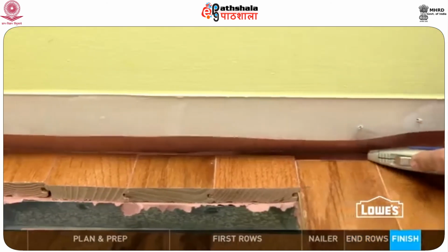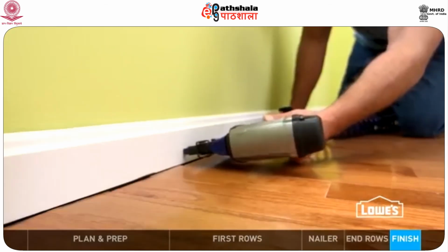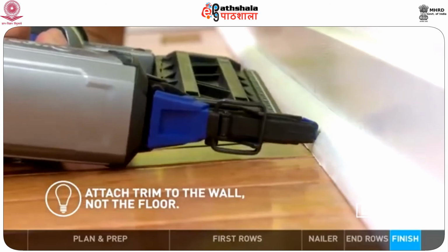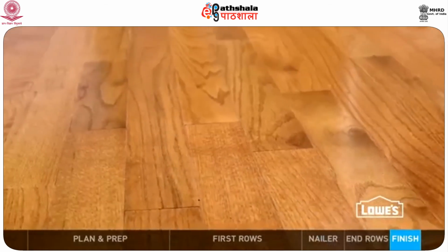Finish up by cutting the excess underlayment, filling nail holes with wood putty, and reattaching the baseboards and shoe molding. Attach the trim to the wall, not the floor. Then add the transitions. And it's finished.